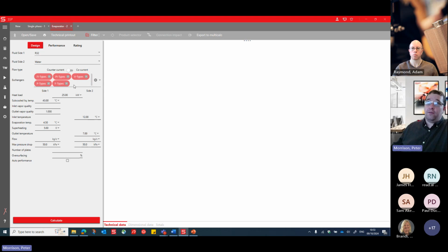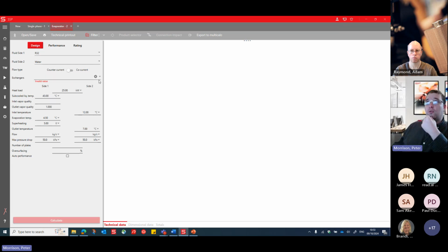These are units that have distribution devices. They're kind of like pipes with holes in them. So it'll get to the first hole, a lot of the gas will try and go up, realize it can't, go to the next hole, next hole, next. That forces it to go the full length of the unit to avoid maldistribution. You can use B types, but we recommend it not be more than 30 plates, just to be aware of that.